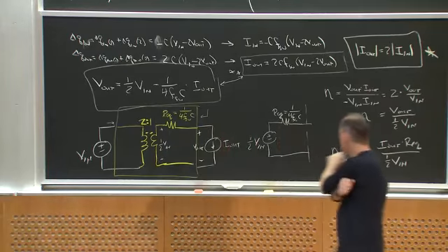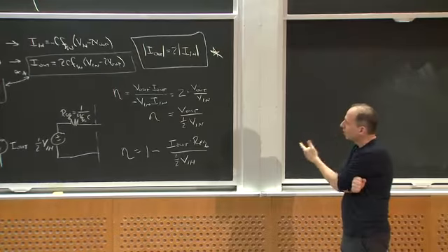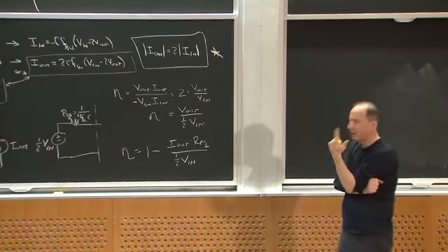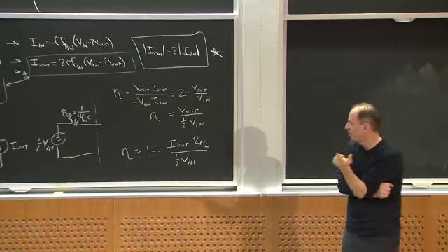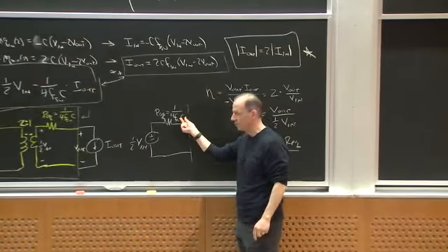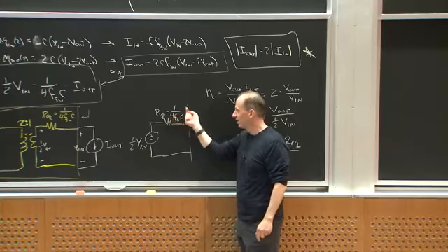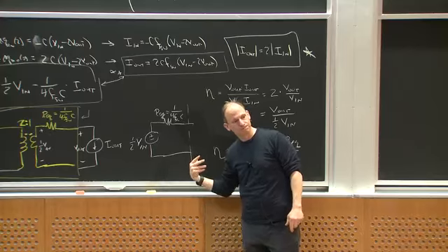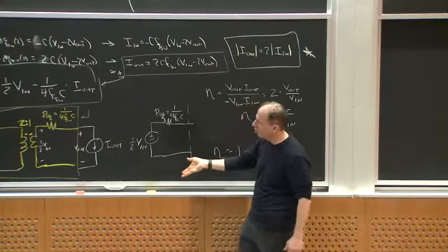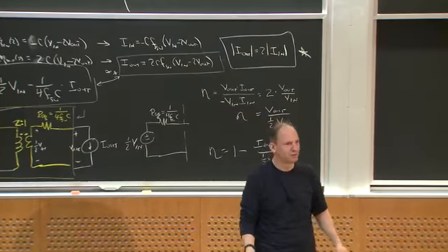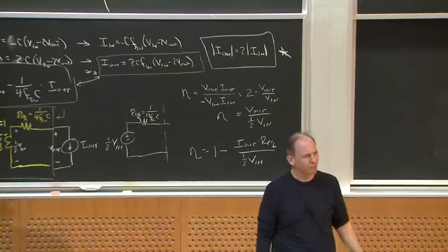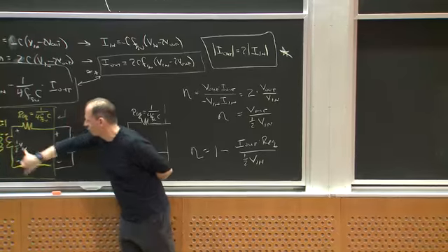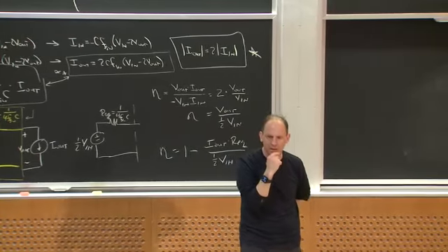So let's think about what other case I might consider. We said, okay, suppose I want to, and by the way, why do we like these converters? Because they can be hyper efficient. If I go buy a really big capacitor here, or I switch really fast, this equivalent resistance can be very small, and I can get an almost perfect 2-to-1 voltage conversion. Okay? And in fact, people would call this thing a 2-to-1 step-down switch capacitor converter. Why? Because they're thinking of the voltage, right? Ideally speaking, if I make this resistance really small, I'm really just doing sort of like an ideal transformer, 2-to-1. Okay? And so people would call that a 2-to-1.